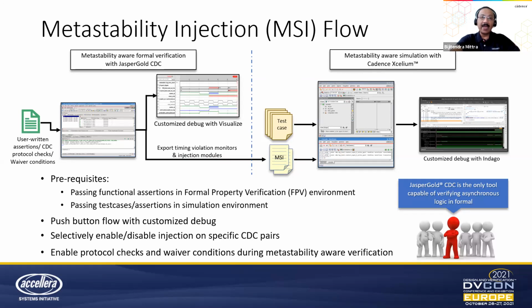And if any of your previously passing test cases fails, you know it is because of metastability. Then the debug process is still the same. You open either Indago or SimVision, and there are injection witness signals, special signals provided by these monitors, which you can plot on the waveform, and you can understand the injection behavior.